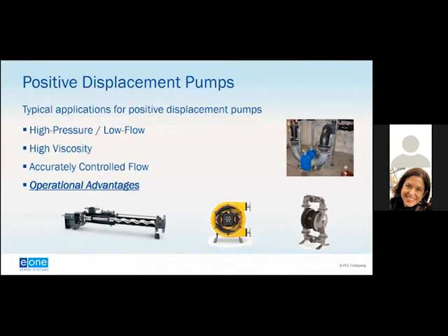Although centrifugal pumps can be designed to generate high pressures through the use of multiple stages, these special pumps tend to be comparatively expensive. So if you do have a high pressure and you're going to go with a centrifugal pump, that would tend to be more expensive than if you just have a typical lower pressure and go with a standard centrifugal pump. Another area where you would typically see the use of a positive displacement pump is high viscosity. Viscosity is how easily a fluid moves through a pipe. So positive displacement pumps are more effective than centrifugal pumps in moving viscous fluids.